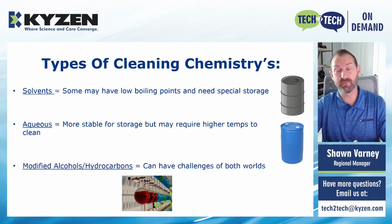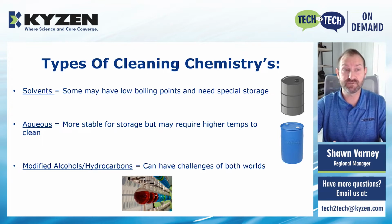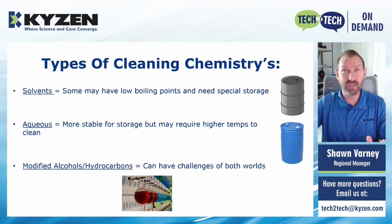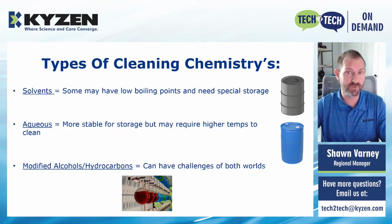You also have your types of cleaning chemistries, which might have some restrictions with the temperatures. So you have solvents, you have aqueous based, you have modified alcohols and hydrocarbons. Your solvents tend to be in a metal container. They may have a lower boiling point and will need special storage. You don't want to leave the lid off of these, as at room temp you'll actually do evaporative loss and whatnot. With the aqueous based, usually going to be in a plastic container. These are more stable for your storage, but may require higher temperatures for cleaning. And the modified alcohols and hydrocarbons are going to have challenges of both worlds, positive and negative, with the solvents and aqueous based.